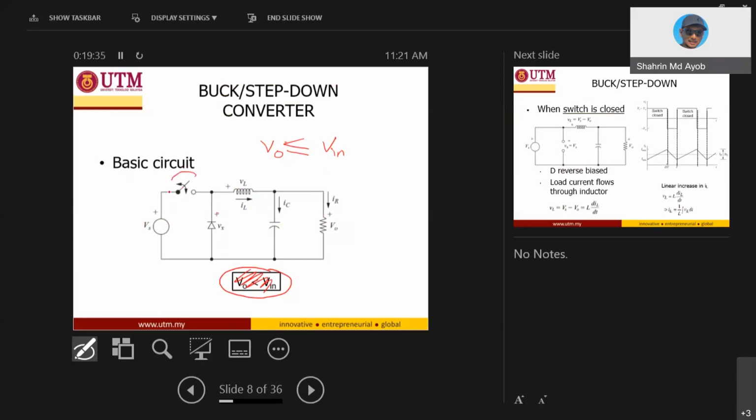This is a switch. It should be a transistor, you cannot use an SCR, because the switch must be fully controlled, meaning that you can control the timing on or off. With an SCR, you can only control on. For this circuit, you need a power switch that is fully controllable, on and off. The only device suitable for this is the transistor. You can use IGBT, MOSFET, or BJT, all types of transistors.